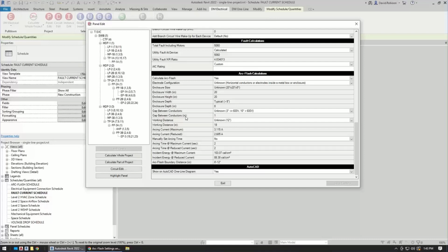You can't just say, okay, at some level when you're doing your design, you're like, okay, panel, transformer, panel, and you're not necessarily thinking about the specific brand and sizing of the panel. That does come into play for Arc Flash. Arc Flash really requires you to know what's going to be installed.